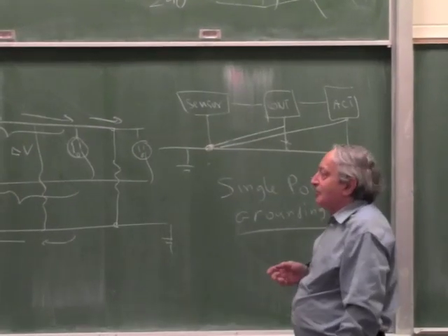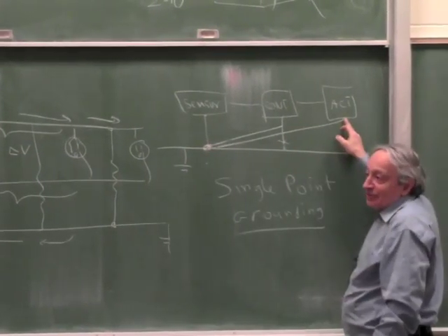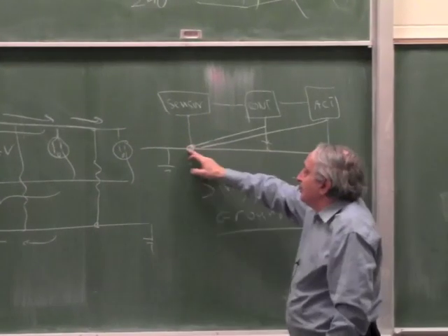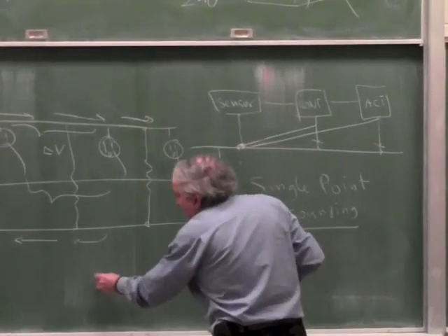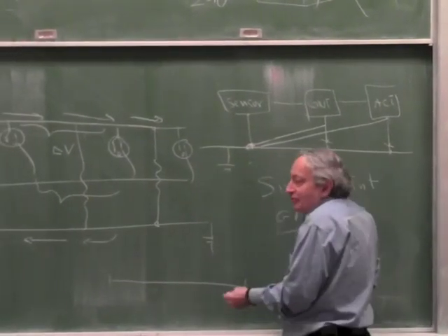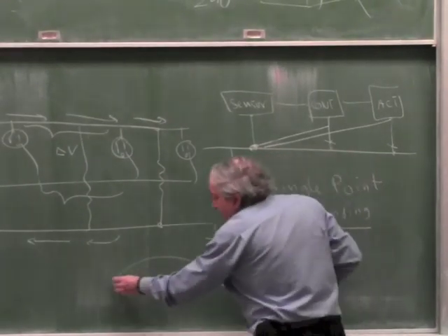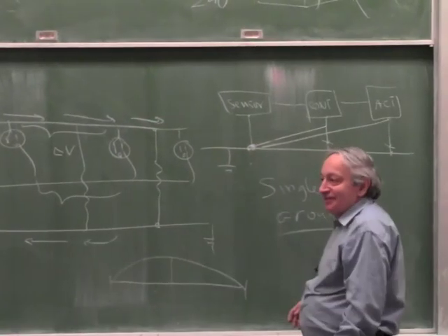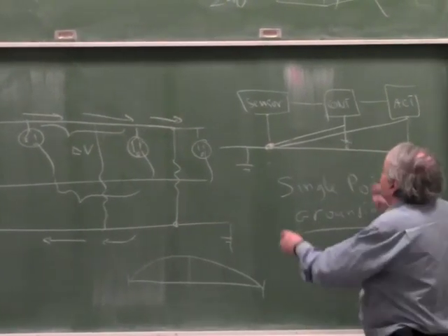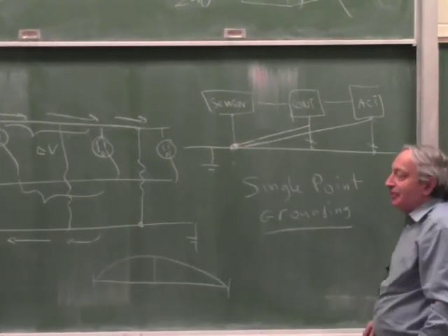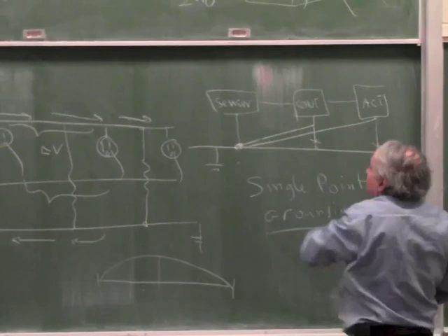And the problem you run into at high frequencies, this can be a fraction of a wavelength, or more than a wavelength, and then you can have 0 here and maximum here on the same wire. Because I mentioned before standing waves. When you have a piece of wire, and this piece of wire is half a wavelength in length, you can have an electromagnetic field which is 0 here, and maximum in the middle. Right? Just like a string of a violin. It can move in the middle and not at the ends. So if these wires become a significant part of the wavelength, the system doesn't work well. And you're better off trying to ground the shortest path anywhere.